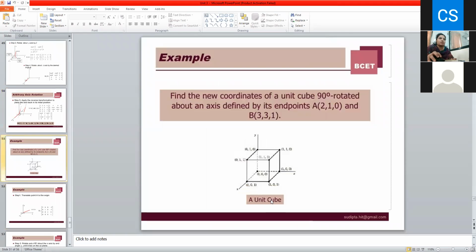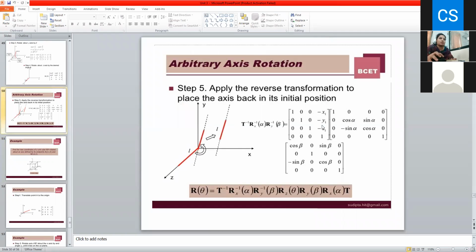And then comes the inverse transformations. So inverse transformation is nothing but these x1, y1, z1 will be plus, plus, plus for T. Then for the rotation angle, the sign values change. Here it will be minus sine alpha, here it is plus sine alpha. So that is the T matrix for inverse rotation about x.